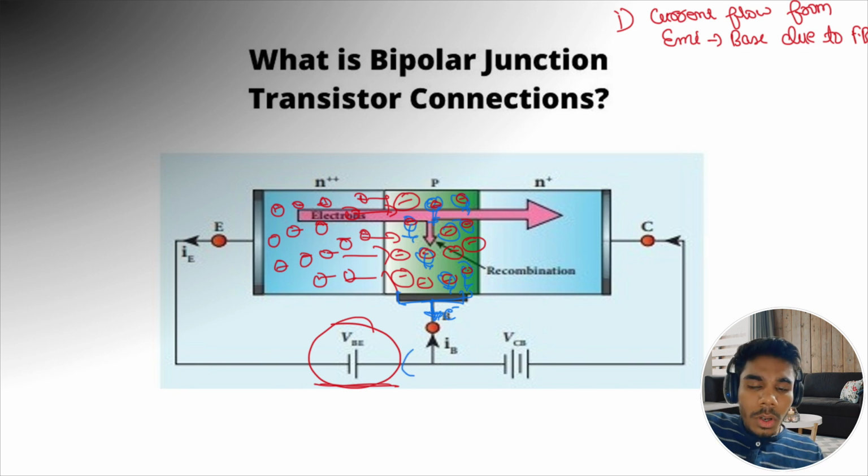So I mean to say that the electrons coming from the emitter will recombine with the holes present in the base, but some electrons are left after recombination due to the large amount of electrons present in the emitter. The recombined valence electrons will start flowing towards the metallic lead connected to the base region, convert into free electrons, and start moving towards the emitter.